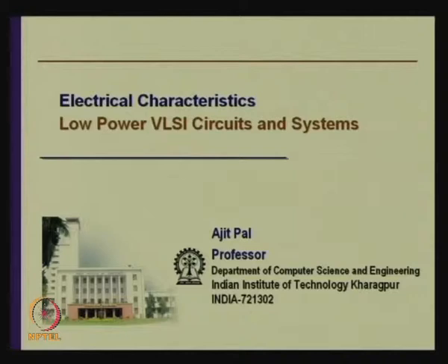And then the strong inversion region is represented by the saturation region. And today I shall discuss the electrical characteristics of MOS transistors.